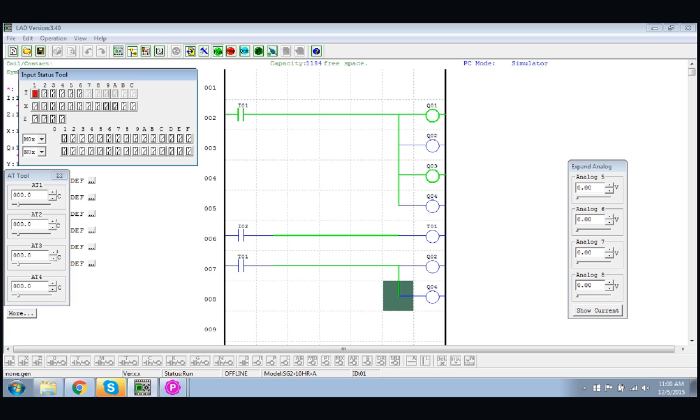Well, why are we not getting 2 and 4? Because this timer is preventing them. That timer is not complete. So this is what we would call AND logic. It's not either or, but both and. So let's close contact 2, and then we see this counting up. 1, 2, 3, bam, it closes, and now we get our Q2 and our Q4.